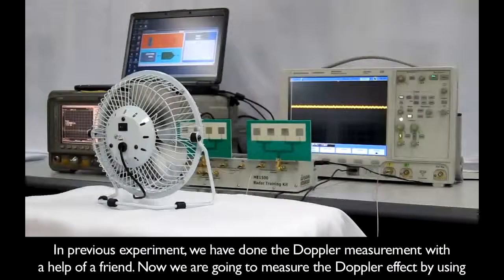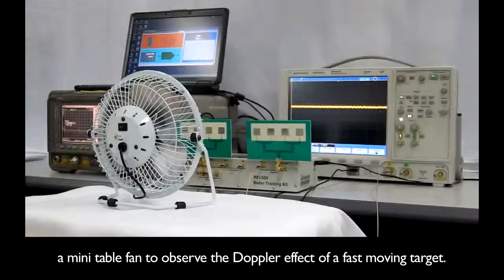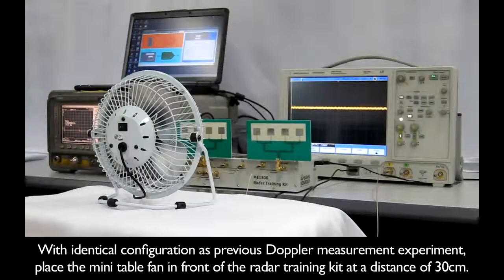In the previous experiment, we did the Doppler measurement with the help of a friend. Now, we are going to measure the Doppler effect by using a mini table fan to observe the Doppler effect of a fast-moving target. With an identical configuration as the previous Doppler measurement experiment, place the mini table fan in front of the radar training kit at a distance of 30 cm.